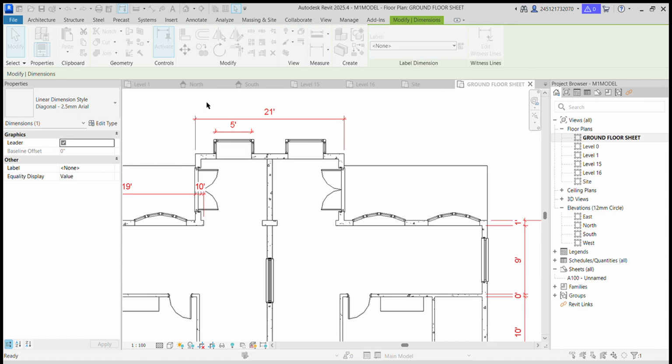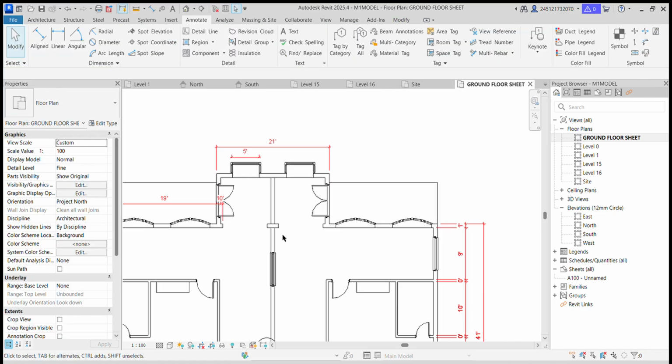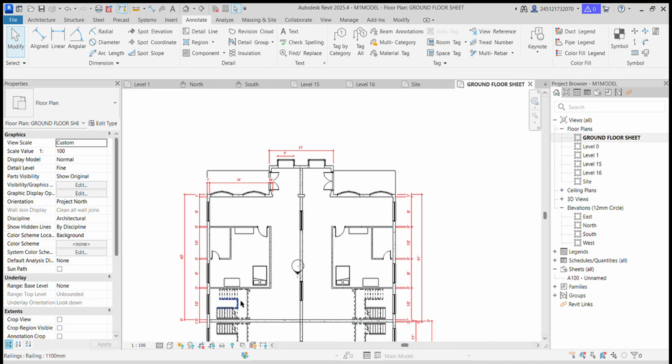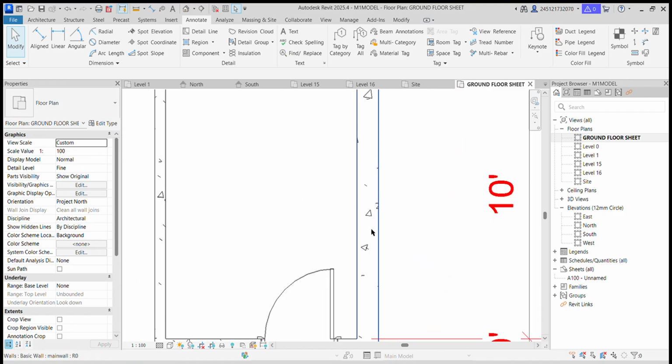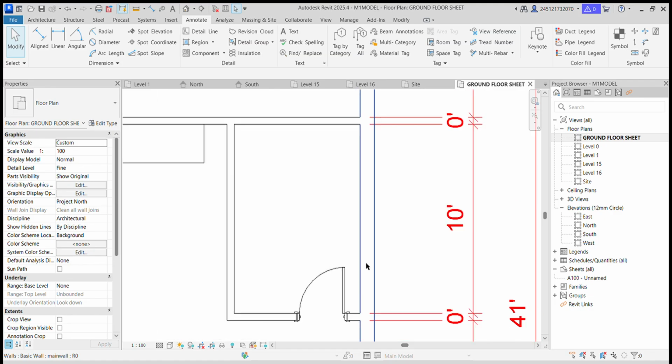Wall comes under the model. Okay, so go to the model. It is under the architecture. Currently you are working with the architecture, right? Choose architecture. All the elements are visible here. And here you can note down, here is a projection surface and a cut surface. We are in the plan view, which means some elements are cut, like walls are cut. If you see the cross section now, that will be hatched, right? So it has a cross section, it is cut.